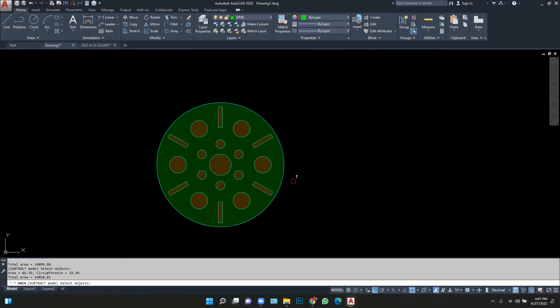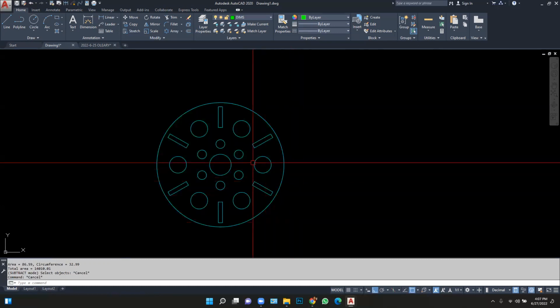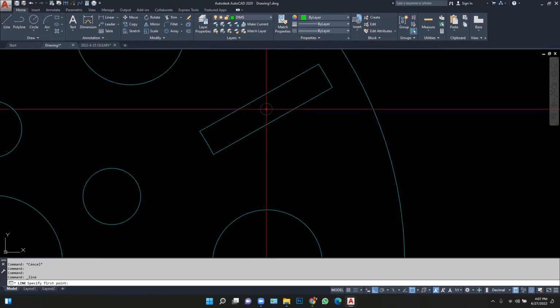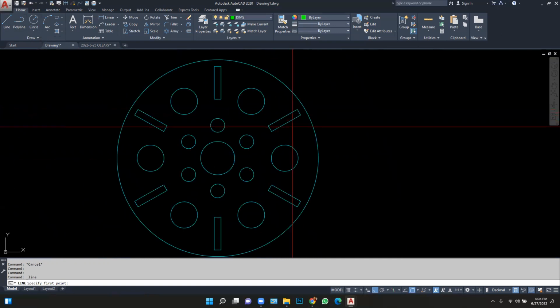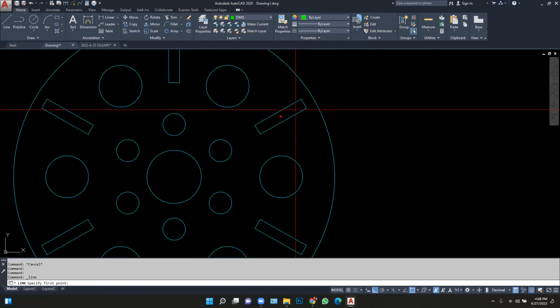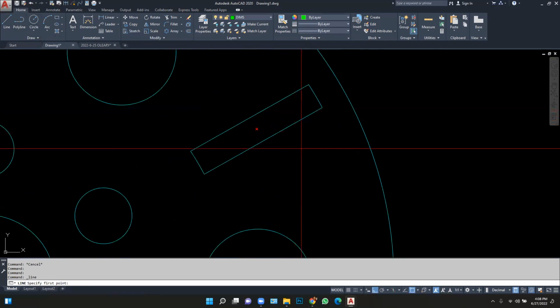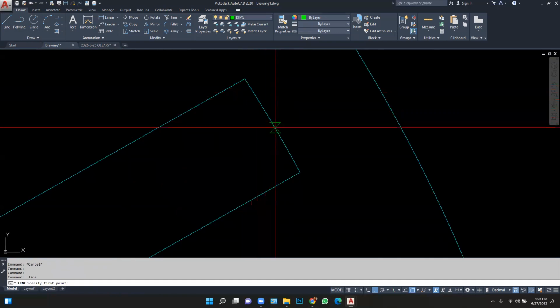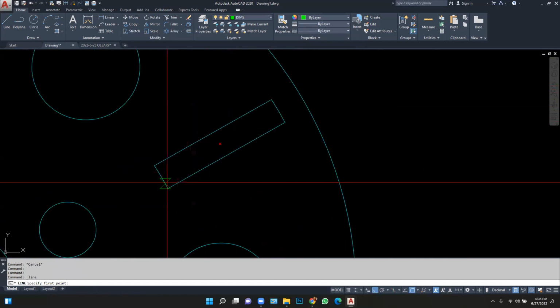The angle formed in the XY plane from the midpoint of line A. This one really gets people because they're thinking the midpoint of line A must be right here, and AutoCAD will actually snap to that, so it tricks you even more. But line A, this thing's a slot. This is not a line. This thing is made up of 2 lines and 2 arcs. It's really hard to tell the arc. Even on here, you barely see that curve, but that's a curve at the top and the bottom.